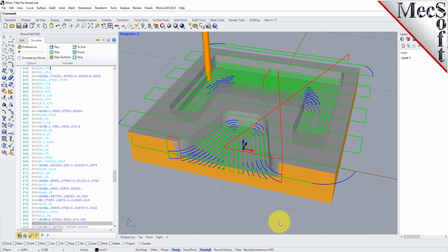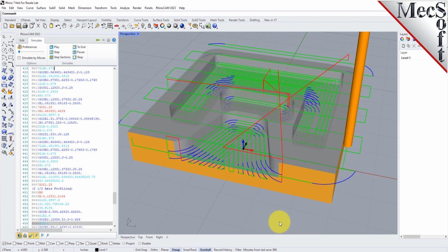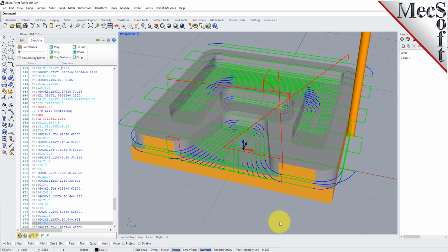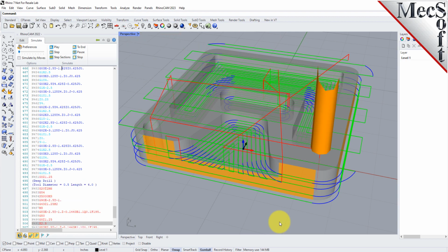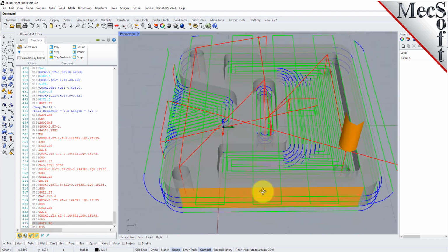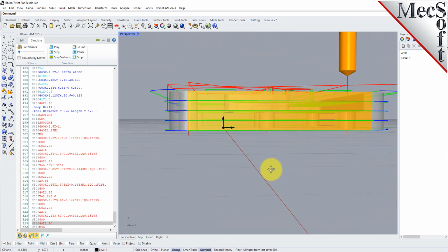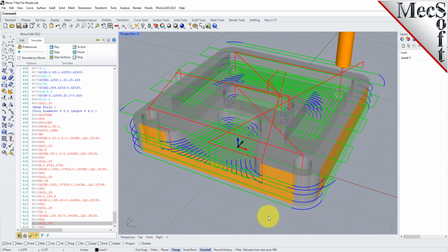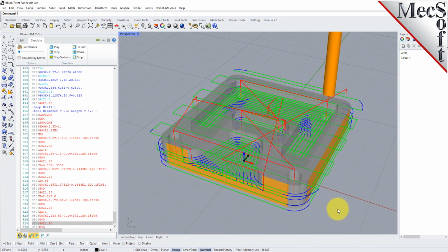That's pretty cool. Now you can see your actual model that was created just from the G-code file. Again, I mentioned previously that you don't have to have a part file. If all you have is a G-code file, you can load it and just define a stock, give it a large enough dimension so that it encompasses your toolpath, and then you can perform a cut material simulation.